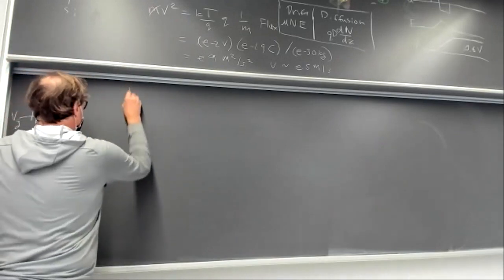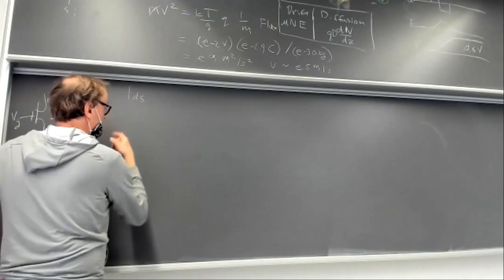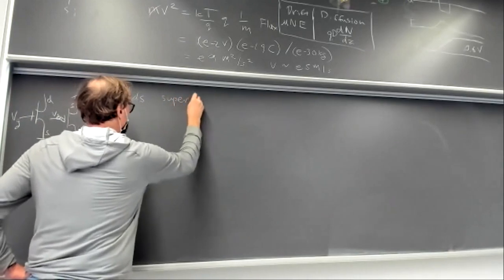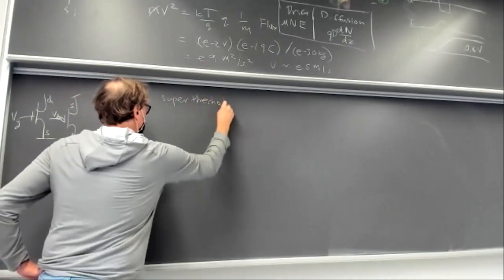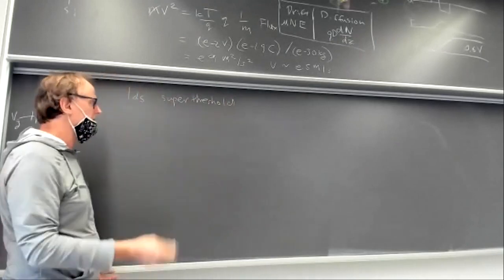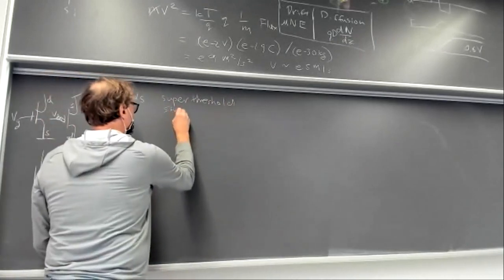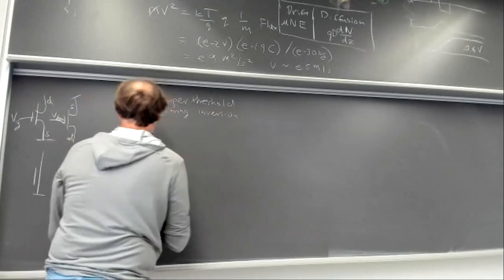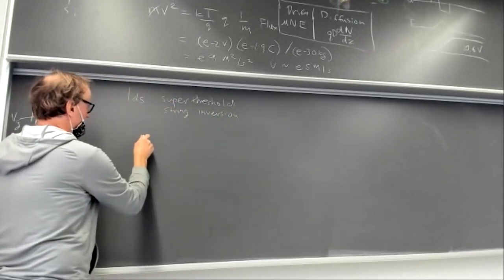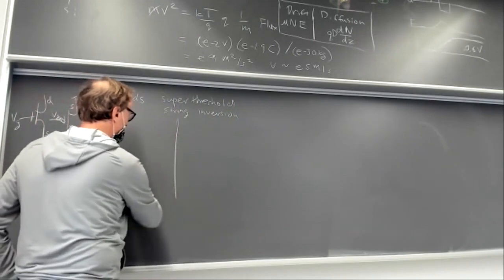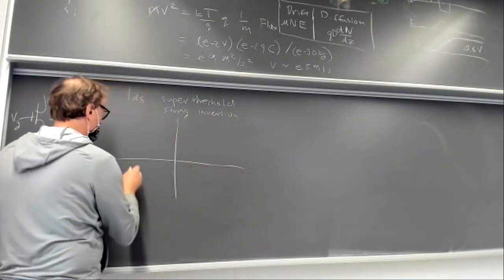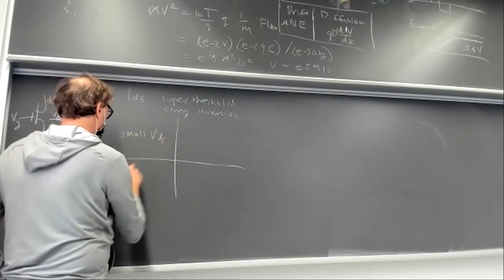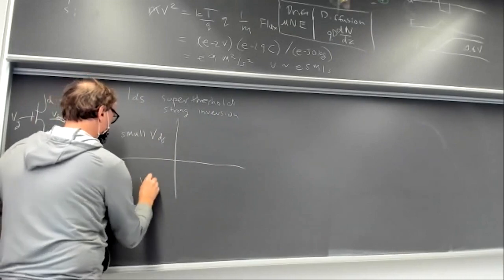So I'm going to write the drain source current above threshold. I need to explain what that means. In super, we call it super threshold to oppose it for subthreshold, but other people call it strong above threshold or strong inversion. I'll explain what that means too. And it's the drain source current as a function of the gate voltage. So there's two conditions: a small VDS, small drain source voltage, and big drain source voltage. Okay.